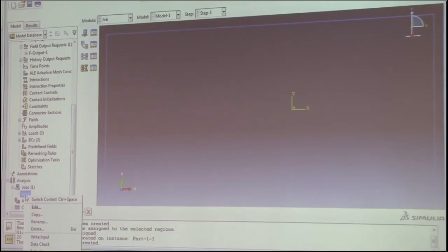Could you please say it again? If your element distance doesn't split evenly into, say, the length of your truss, what is that basically? You can set it differently, one by one, defining it in the way you want. I just use 0.2 for the whole model, but if you want, like, 1 element here and 10 elements here and 2 elements here, you set them one by one separately.